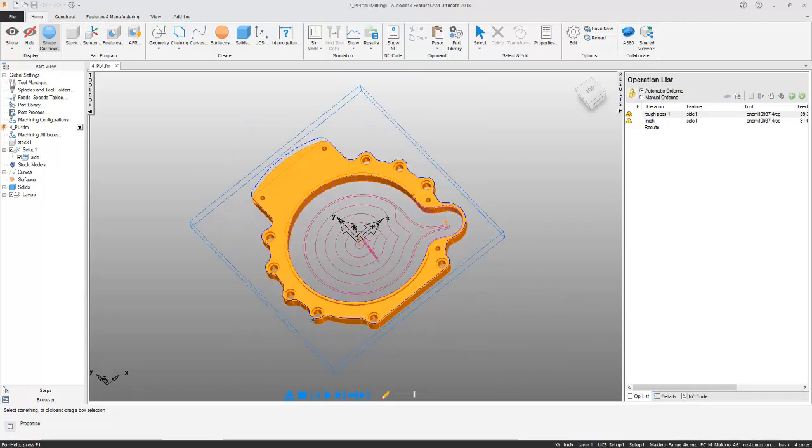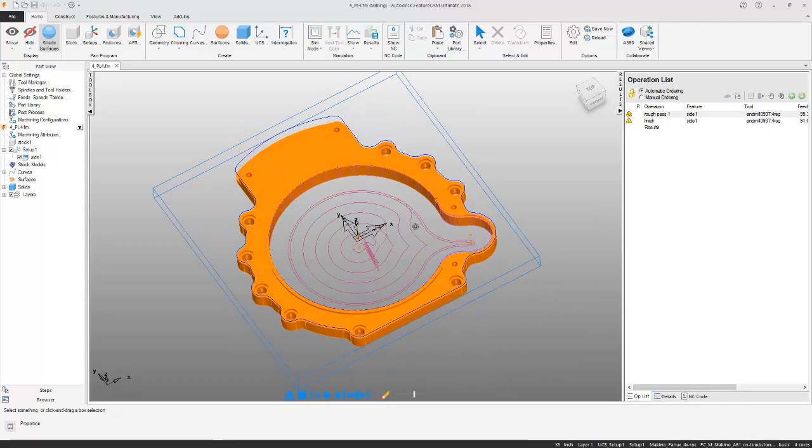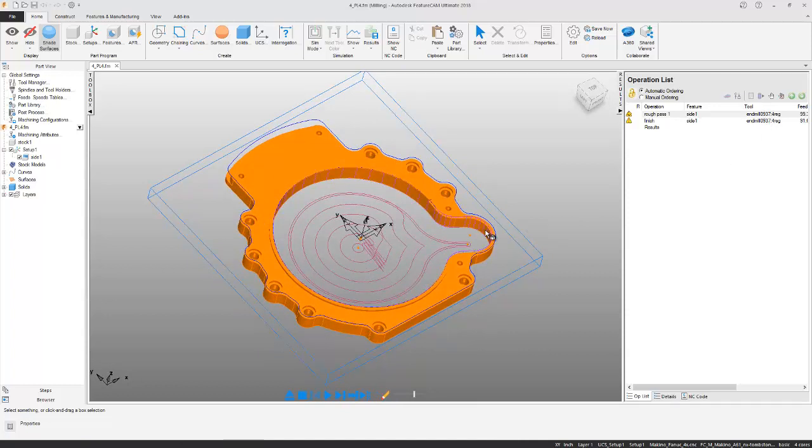And you can see just standard spiral toolpath, a single tool, but I want to create this pocket using the stored process that I have. Now, I was thinking ahead. There's some strategy and some planning involved here. I defined it as a side feature, so that will give me the ability to paste side feature attributes to it. So I'm not going to new feature in this case because I already have the feature.